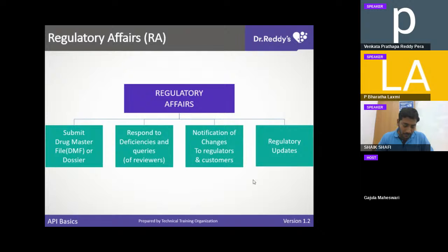Basically, we use different types of standards. Let us take the example of a weighing balance. We take different types of weights. These weights are approved by the legal metrology department, a government authority. Let us say we need to check the calibration performance of our weighing balance.